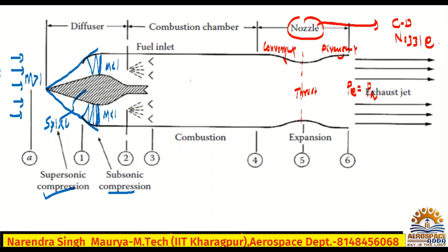Like in the combustion chamber, obviously the flow will be less than 1, meaning subsonic flow, and again in the short CD nozzle it will be accelerated, so again the flow will be greater than 1, meaning supersonic. In a ramjet, you know very well, combustion always occurs at subsonic flow. But in a scramjet, that's the next version of the ramjet, supersonic combustion takes place.